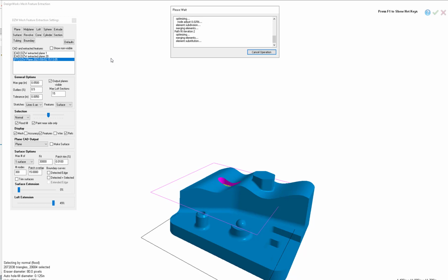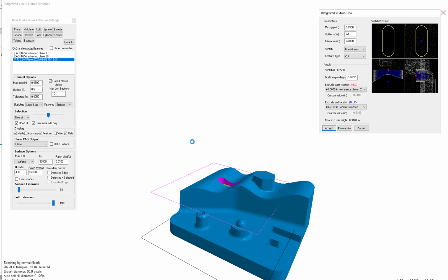Now, if we normally just cut that with what we painted on, when it intersects that loft, it could end up being divisible by 0. So what we could do here, you notice here it showed me where this is at. We could actually just say cut, and down here where it's blue, we could actually say through all. So see the little window, how it updates? You can change this through all or a value, and you'll see this all update.